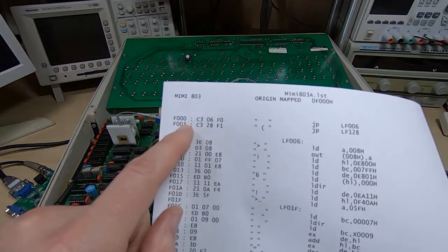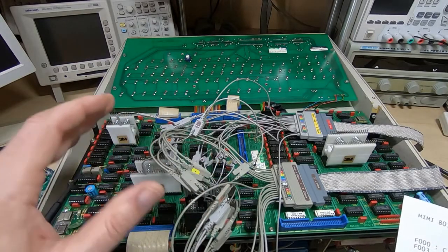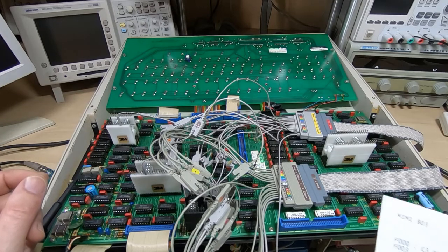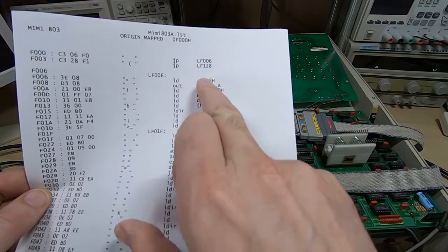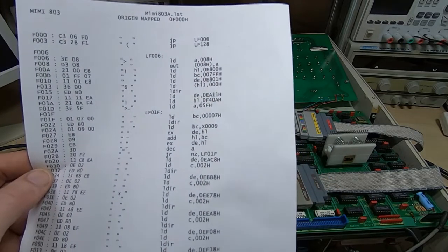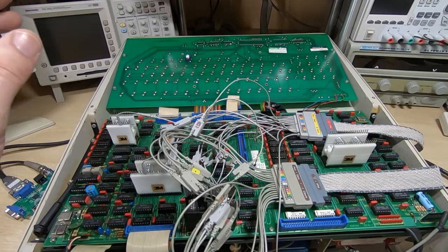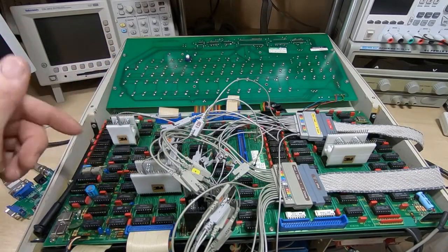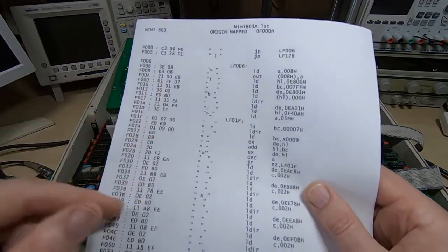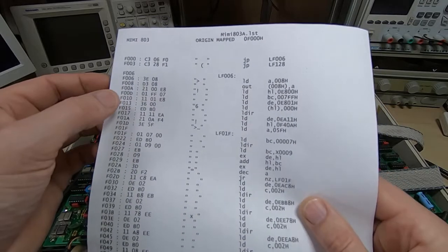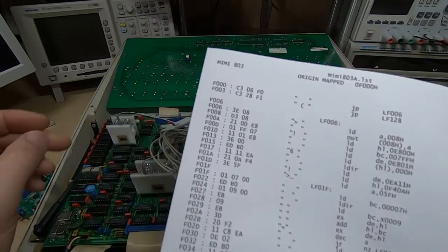Although we've got address up here of F000, as far as the Z80 is concerned, it's mapped down to address 0. And then you probably find that these first few instructions, these out instructions, almost certainly are intended to change the mapping within the system. And what it then does is it allows the Z80 to boot, see the ROM, and then it can configure the system accordingly. And from that point on, of course, all the addresses can be correct because the Z80 has now been vectored to the correct memory address. So that's basically how it works.